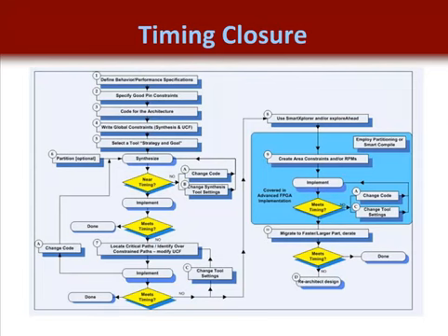This flowchart is used extensively as part of our Designing for Performance course. And in that course, our primary objective is to show designers how to meet all of their timing needs. In this diagram, the first 4 steps in the upper left-hand corner describe the high-level procedures that all designers must follow early in the design process. These include making good pin assignments, understanding what a reasonable timing objective is, building their HDL code so they can get the optimum FPGA resources in their design, and making good timing constraints to be used during synthesis and implementation.